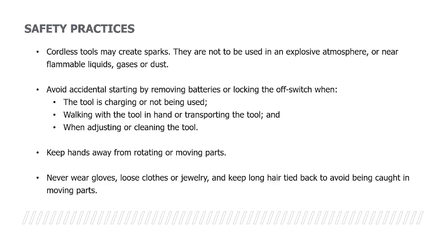Keep hands away from rotating and moving parts. Just because it's battery powered, folks, doesn't mean it will not cut you, and it will. Never wear gloves, loose clothes, or jewelry, and keep your hair tied back to avoid being caught in moving parts.